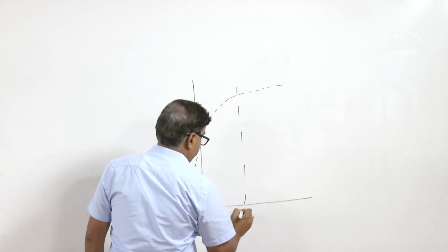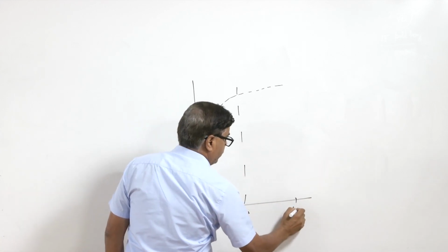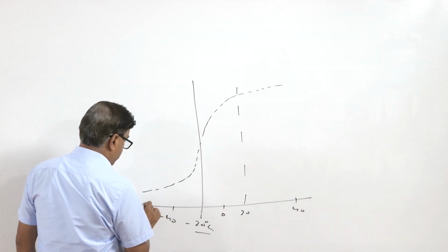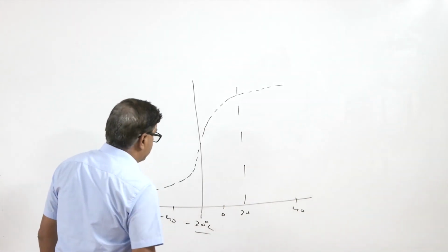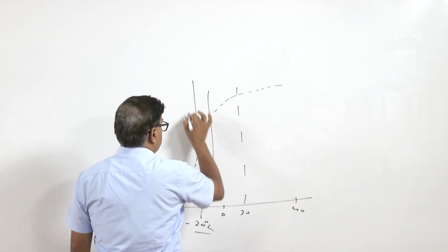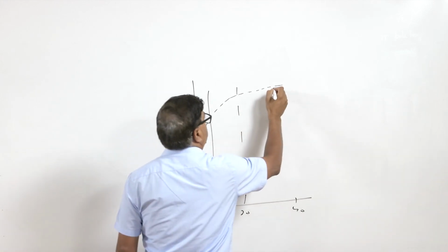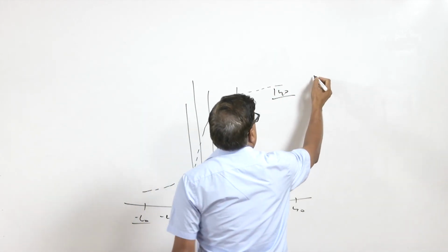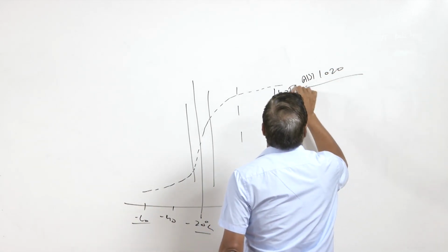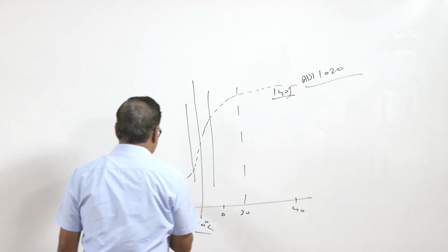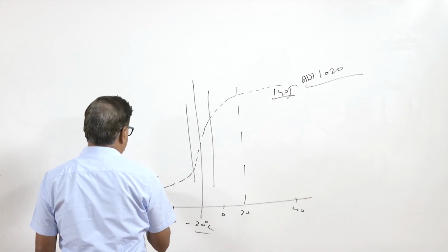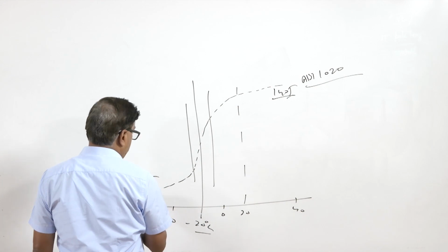So, at room temperature, say it is 20, then 40, and here somewhere 0, then minus 20, minus 40, minus 60. What it suggests is that as soon as we come down below minus 20, there is a very sharp drop in the toughness value, which for simple carbon steel AISI 1020 is 140 joules, and may get reduced to almost 10 to 15 joules.